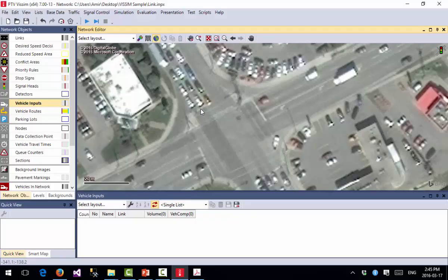They know only the flow of the traffic, and they put some people here to do some observation. They see that there's a 10% turn ratio to the right, so you have a right movement of 10%, 75% through movement, and 15% left turns. You will have the same information for all of the approaches to your network area.